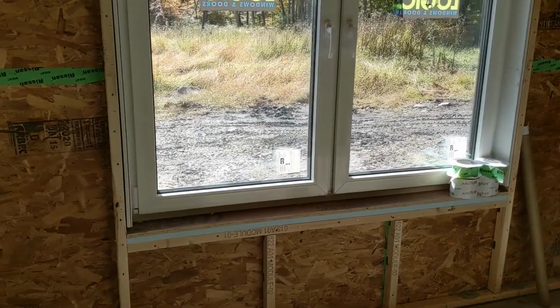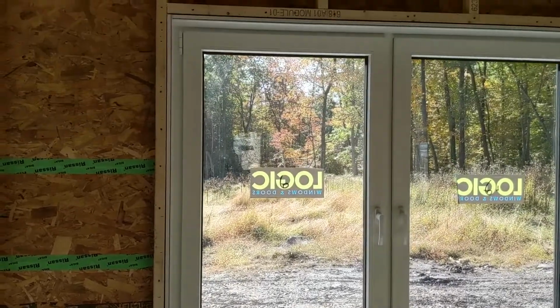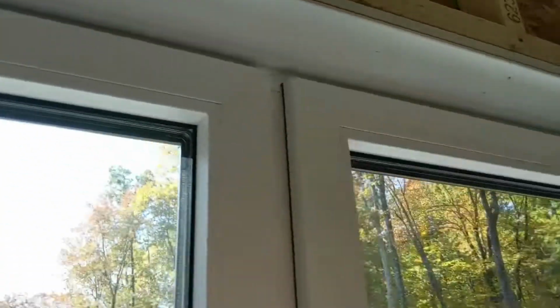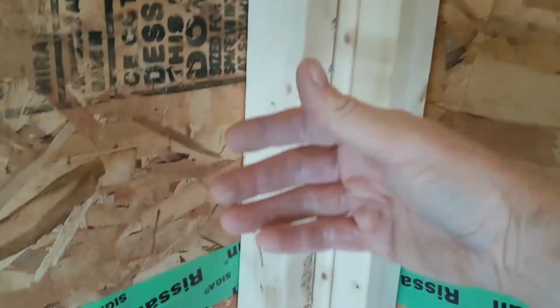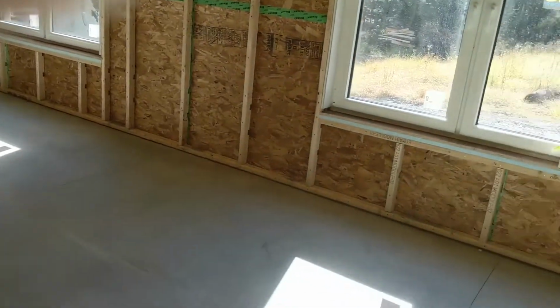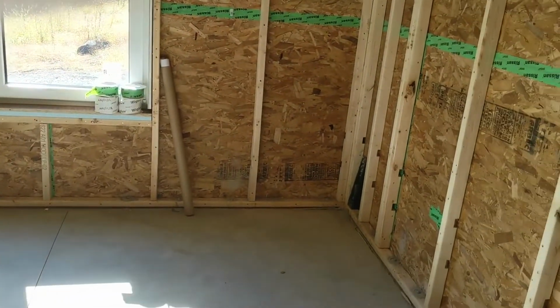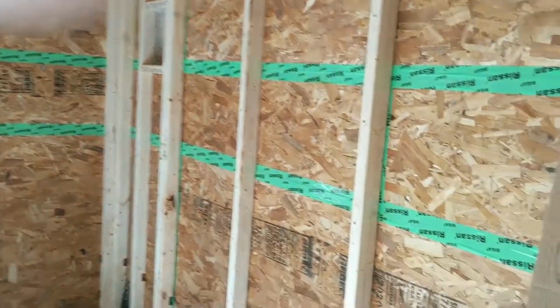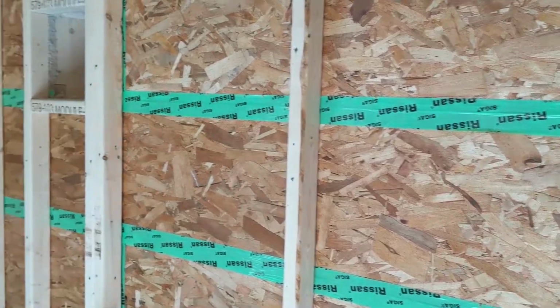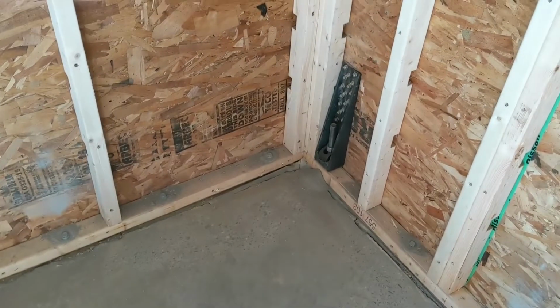I'm going to use a very sophisticated and sensitive tool for finding air leaks, the back of my hand. I'm going to focus on the intersections or the joints, basically, just trying to feel for air leakage around all the windows and all the corner joints, where there's any penetrations, plumbing pipes, electrical conduit, at the base of the walls on the first floor, at the tops of the walls at the second floor. It's fairly easy to air seal something that's two-dimensional coming together, like these joints in the inner air barrier, the OSB. Where it gets tricky is when you have three things coming together, so that's really where I'm going to focus.